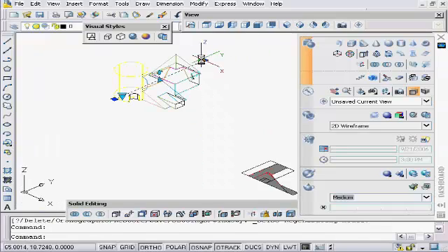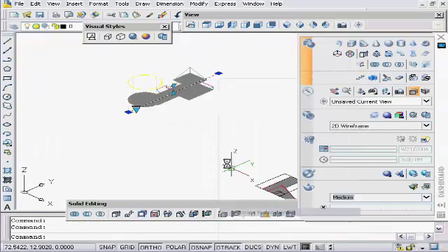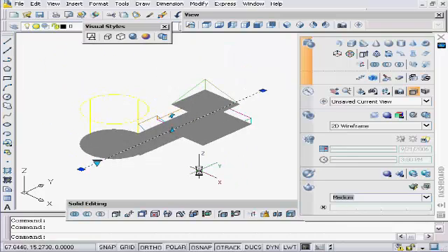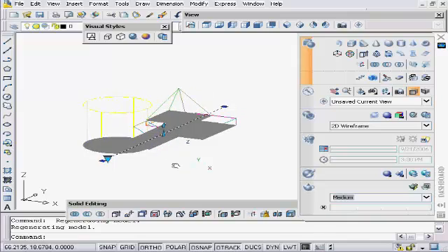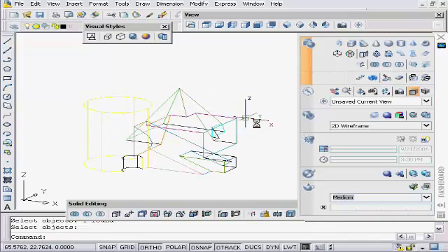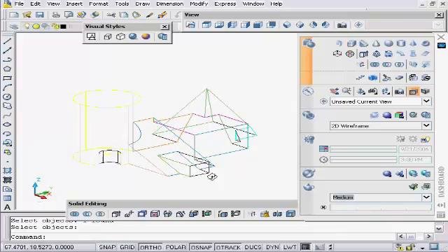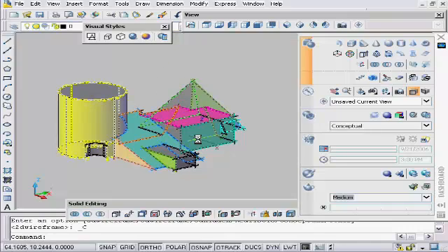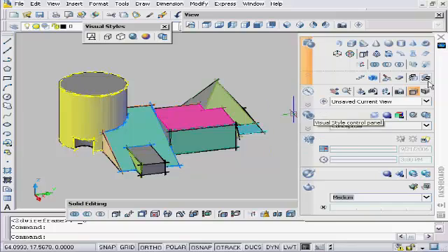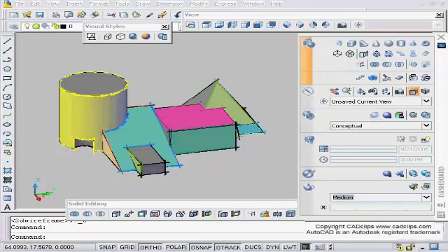Move that back over to there, go to our 3D view, click on here, right click, enable that live section as you please. So they can be placed in plan, in elevation, in section, in a 3D view. All your settings, right click on it, have a look at the options, right click everything every time, wherever you get a chance to, and then use your grips as well to manage your section planes.